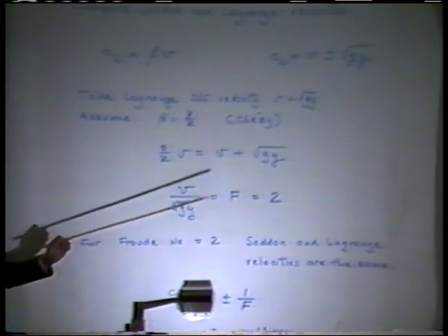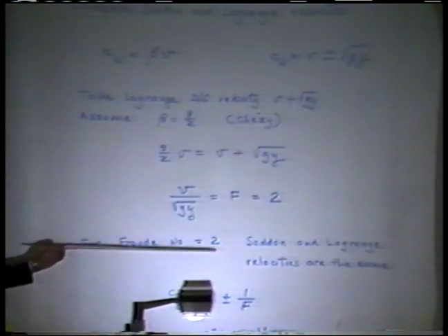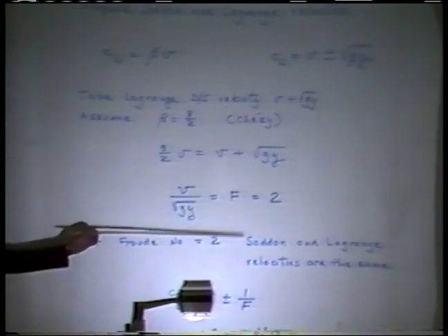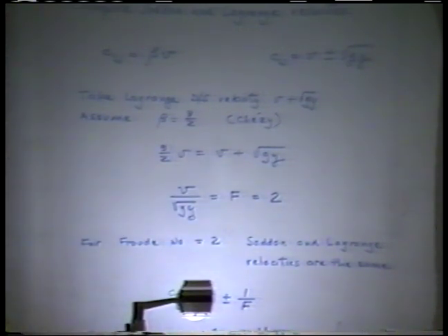So in order to determine this onset, this threshold of Froude number or free surface instability, you would have to not only determine what the friction is going to be, whether Manning, Chezy, or any other, well actually there's only two, but also the cross-section. What is the cross-section going to be like? If you have a rectangular channel, wide channel, then it's going to be that. But if the channel looks like this, then it is going to vary.